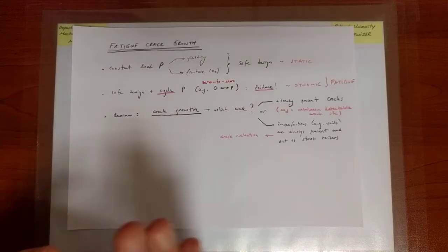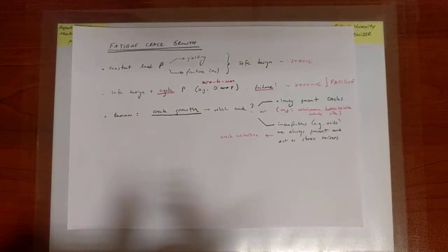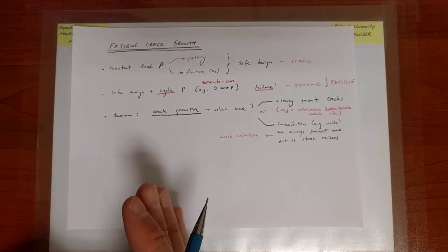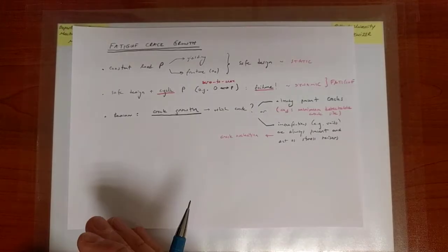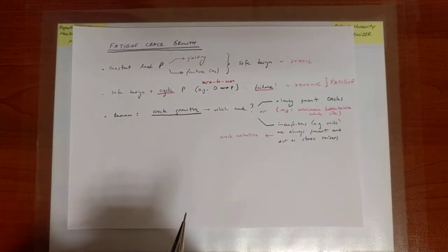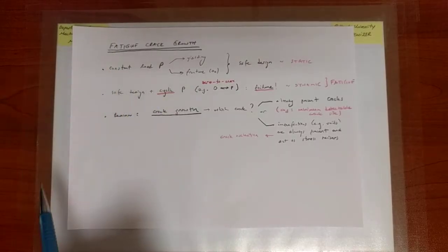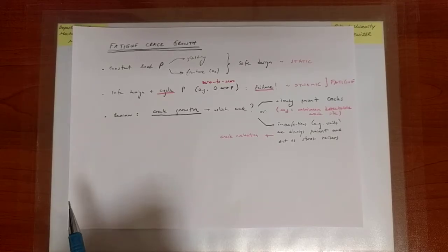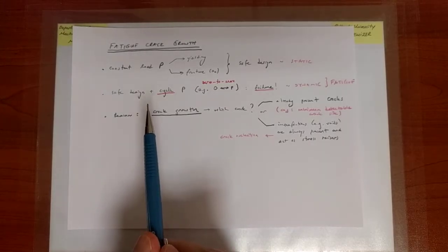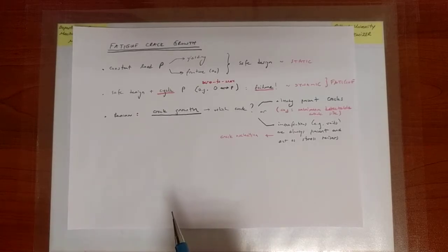We're going to look at a very ideal scenario, a single crack that will eventually grow over time. And as we move into this type of physics, where we look at how things vary over time and how the imperfections grow, the mechanisms that govern the physics of crack growth and eventually fatigue are rather complicated, and to this date nobody can say that they have an absolutely full understanding of what is going on. And for that reason, the topic is heavily guided by experimental input.